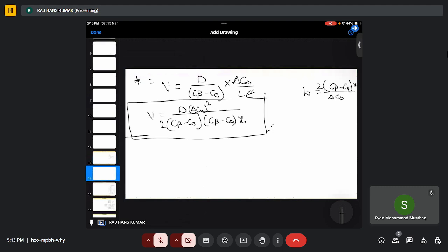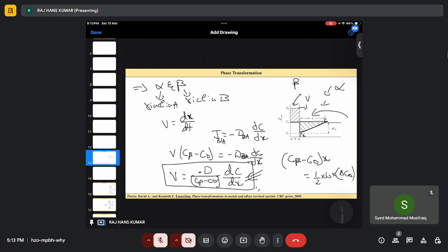Right. Now, we have studied the diffusion mechanism of how the precipitates grow and how the undercooling and temperature affect the nucleation rates and the diffusion of atoms to form precipitate. Also, the velocity front will increase if there is a concentration gradient between the beta precipitate and alpha. So that is very important to remember. What is my delta C naught?